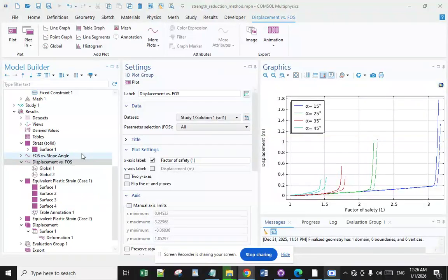Engineers frequently use the factor of safety as a measure to evaluate slope stability, and it is widely recognized as a reliable safety indicator because of its practicality for engineering applications. The proportional reduction approach was employed by one researcher to assess the stability of a concrete dam, and other researchers used a new finite element method scheme to develop the limit equilibrium equation for different proportional reduction parameters. They also explain the rationale behind using different proportional reductions for the cohesion and friction angle.